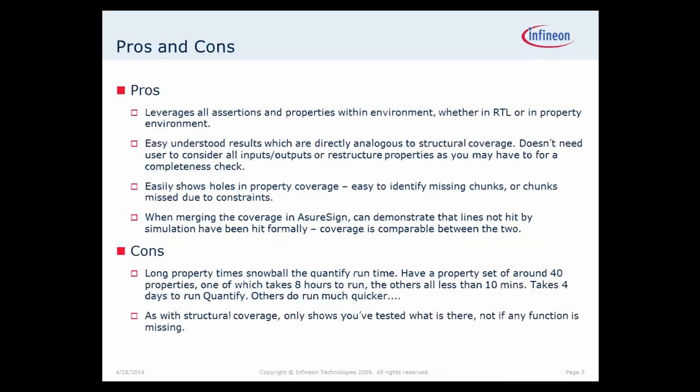So the pros and cons of using this: it leverages all of the assertions and properties within the environment. So whether your designer has written them, embedded them within the design, saying these are the things I expect to happen, or whether the verification engineer has written formal properties to try and prove functions, they can all be used together.